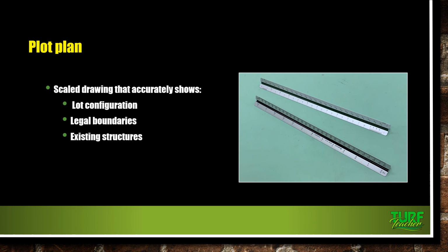There we have a couple scales, guys, you should be familiar with this. Most of the plot plans that I am typically seeing in the job site boxes are 1 inch equals 20. I'm also seeing 1 inch equals 30. Sometimes I see 50. Just depends on the surveyor. So we would take that survey and actually blow it up.